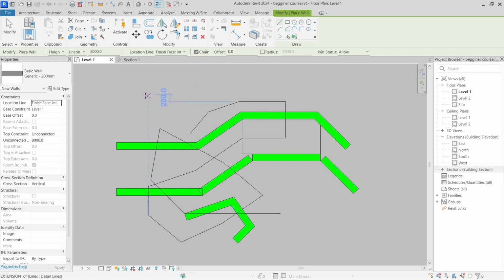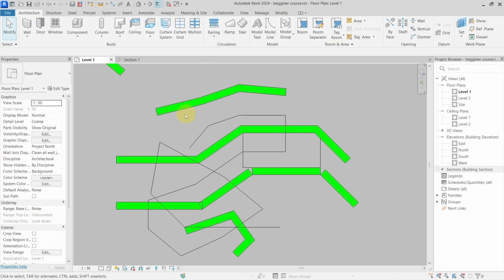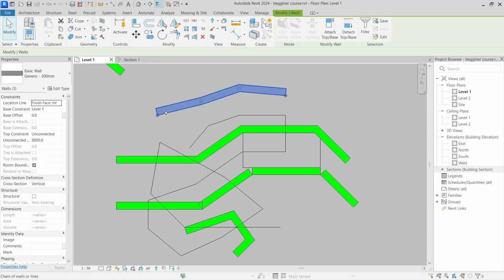And if I create my walls with this chain selected, like this, and they are joined together, later when I am trying to select them, if I hit my tab key, you can see that I am able to select the chain of walls. So I can select all of the chain of these walls, and if I hit my left mouse button, it will select them all. The same goes in here. You can see that I can preview and select all walls at the same time.